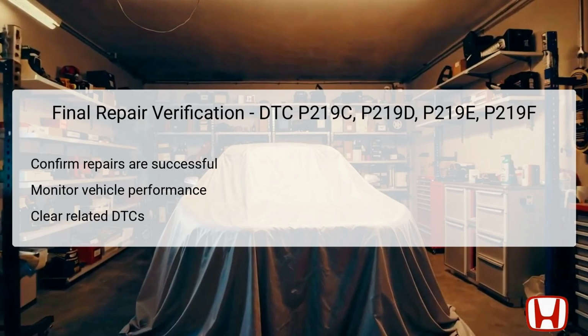Following this, monitoring the vehicle's performance is essential, ensuring that it operates smoothly without any abnormal hesitations or irregular engine sounds. Also, it's critical to clear the related DTCs from the PCM to reset its learning parameters.